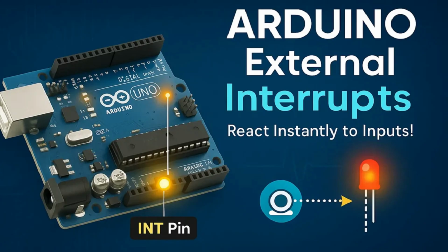Before we jump into the code, let me quickly explain what external interrupts actually are. Normally, your microcontroller runs through the main loop, the while(1), doing whatever you told it to do. But sometimes something urgent happens, like a button press, and you need the MCU to stop what it is doing and respond immediately. That's exactly what an interrupt does. It literally interrupts the main program, jumps to a special function called the ISR, interrupt service routine, handles the event, and then comes back to where it left off.